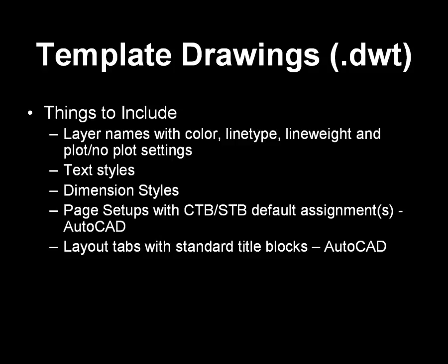So what should be included in your template drawings? Well, actually, let's back up. What is a template drawing? A template drawing, very simply, can be any DWG file that you change the extension to a DWT. So there's really no difference in the file format other than that extension name change. But a template drawing is the starting place for all of your drawings. So you can assign a template drawing, and every new drawing that you start in AutoCAD or IntelliCAD will use that template drawing as its starting place.